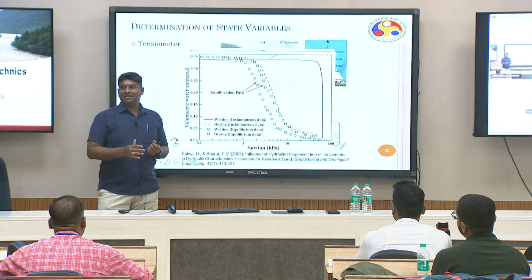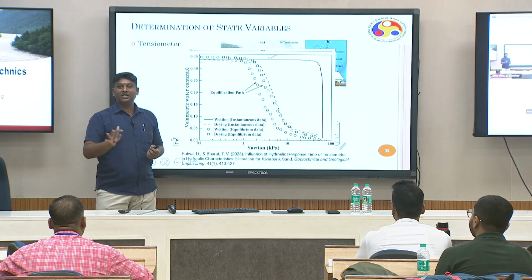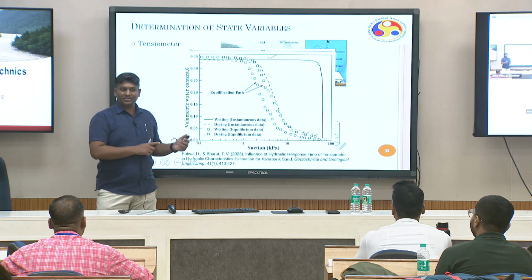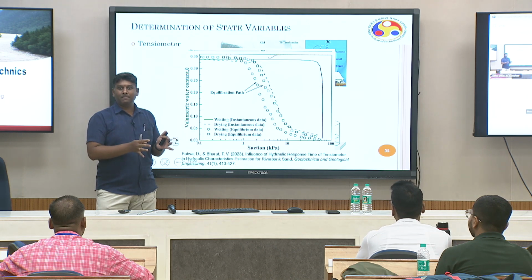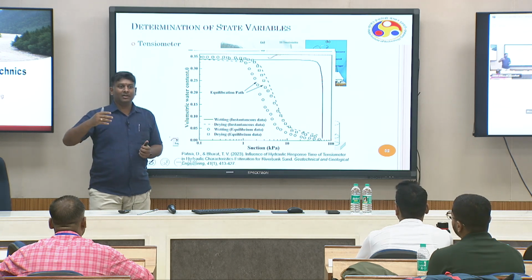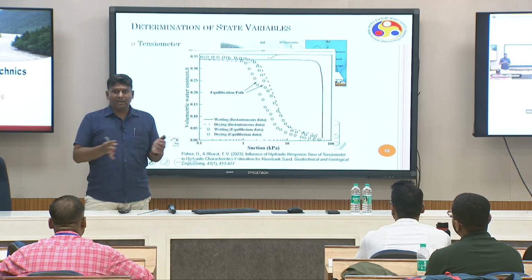It's not correct. So therefore, I don't recommend using suction sensors in the field. You should establish SWCCs in the laboratory for a representative soil sample, then measure the water content. Water content is a very quick method. Immediately it gives the reading. The variability associated with the atmospheric conditions, the soil variation, soil moisture variations is very quick.